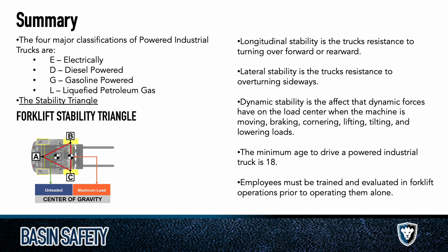Again, the center of gravity is going to be right in the middle of these things, which will change with the height. So you have your counterweight, which is A, your front tires, which are B and C, and right in the middle there is your center of gravity. Again, that's right at the ground level, maybe an inch or two higher with the load down at the ground, and then as you lift that load up, that tends to go higher. So we want to kind of keep that in mind.